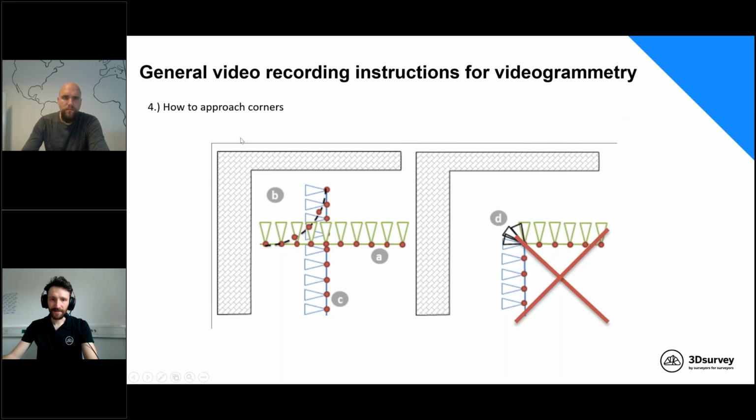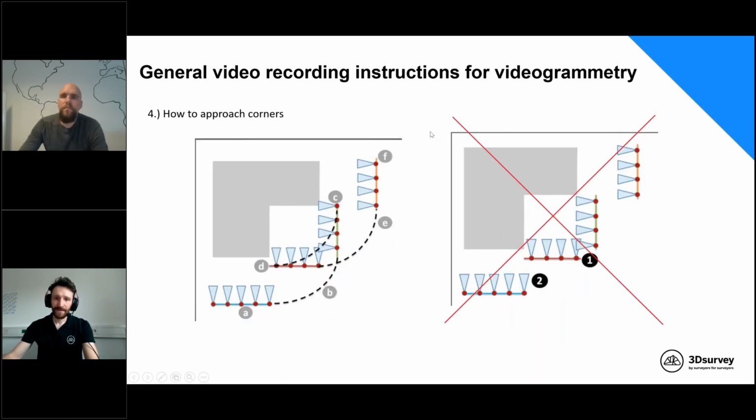And here is an even more complex case. It is very difficult for a photogrammetry program to match images that are, for example, shot like in the right picture. That's why you have to connect those in semicircle or quarter-circle lines that form a smooth line which has enough overlap and doesn't have sudden angle shifts,